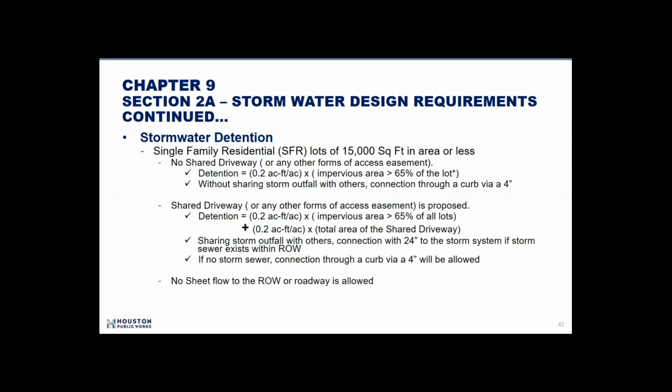Each one of those will be treated as individual lots, because we say single-family residential lots are 15,000 square feet or less. So this is basically the equation that we want you to use: 0.2 acre-feet per acre times impervious area, that's anything greater than 65% of the lot.